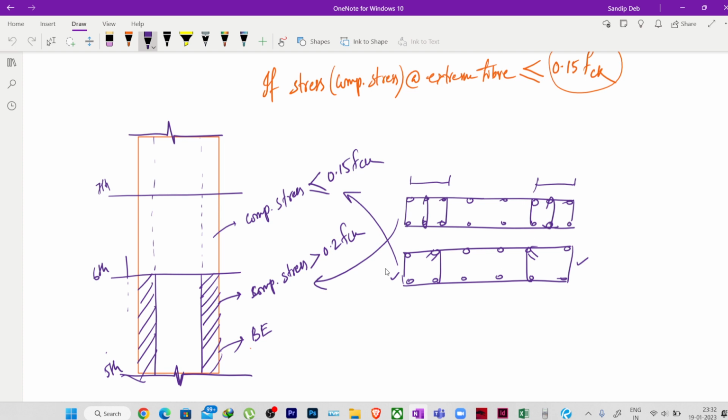So we can calculate the general reinforcement in the whole shear wall, and then we can just provide a column like arrangement at the ends. And the length, you can decide, will be between 2 times TW to 0.2 times LW. Fine.